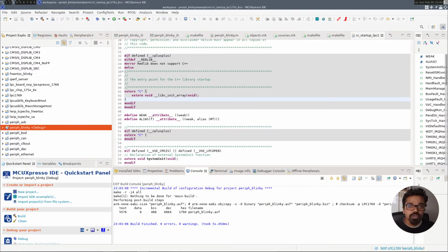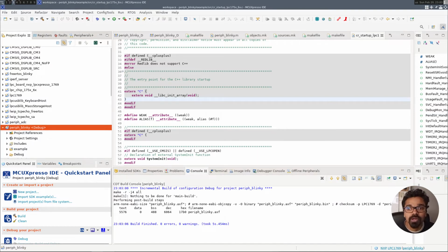So just to continue what we did from the previous video, in here I basically downloaded the environment of the manufacturer, imported all the board support packages, and compiled it. It's very important for you to do this step, because you need to figure out how the build process is actually done, because we're going to take the way they build and what files they're linking against, for us to basically do this in our custom environment.